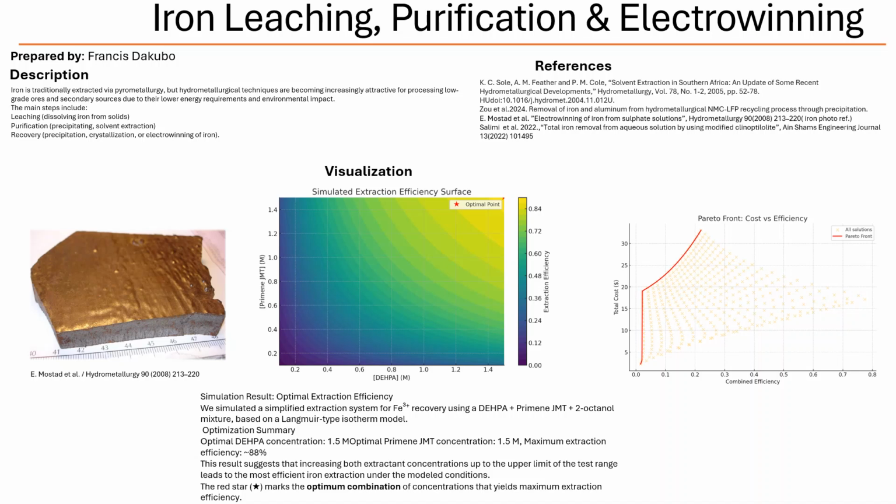What about the operating conditions? What did those look like? The feed solution had a pH of around 2 and an iron concentration of 55 to 65 grams per liter, mostly in the ferrous form. The catholyte was similar in pH, but with less iron, around 25 grams per liter. The anolyte, on the other hand, had a higher iron concentration, with a significant portion being ferric iron, Fe3+